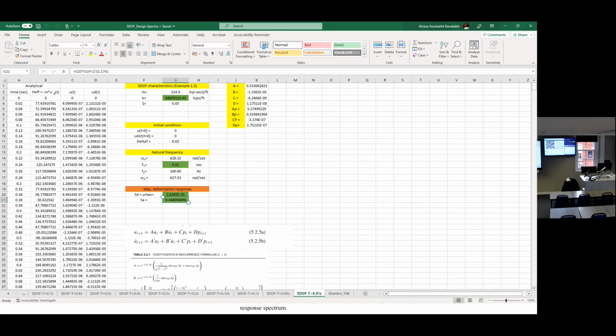just to better show it in terms of percent of g, not feet per square second. It's okay, you can not do that. You can represent it in terms of feet over square second. But it's better. We usually represent spectral acceleration in terms of the percent of g. So if I represent it in a percent of g, if you want to work with feet, you can multiply by 32.2. If you want to work with meter over second squared, you can multiply by 9.81, right? So I got SA here. This is the SA, which is the maximum, coming from the maximum response.